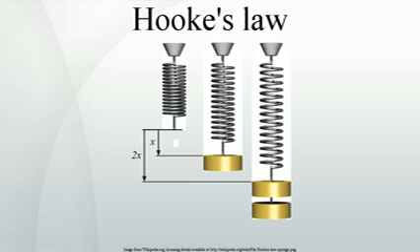The first term on the right is the constant tensor, also known as the volumetric strain tensor, and the second term is the traceless symmetric tensor, also known as the deviatoric strain tensor or shear tensor. The most general form of Hooke's law for isotropic materials may now be written as a linear combination of these two tensors, where K is the bulk modulus and G is the shear modulus. Using the relationships between the elastic moduli, these equations may also be expressed in various other ways.